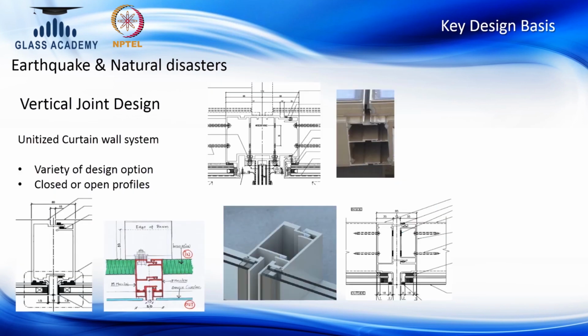We are still continuing with the joint design. Facade system has no definite rule for using a particular standard profile, unlike steel design. In steel design we have standard profiles like an I-beam, C-channel section, angle section, or a hollow section. But for curtain wall, the engineer should be familiar with what is available, what is possible, and what the limitations are here. And you can see in this that the profiles which are supporting the facade system have no definite shape. It could be many different shapes here.